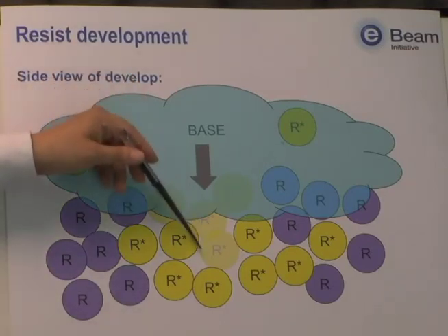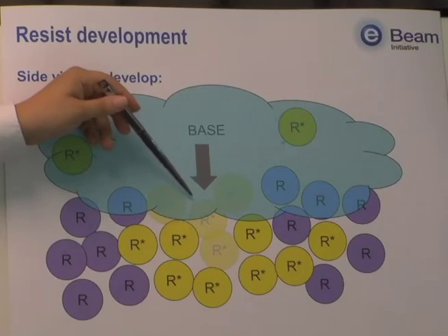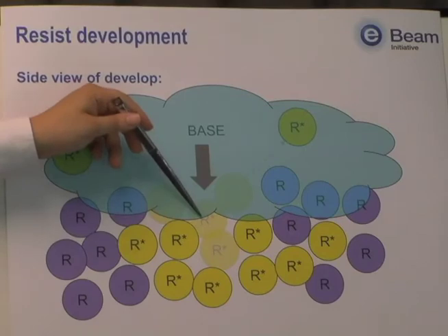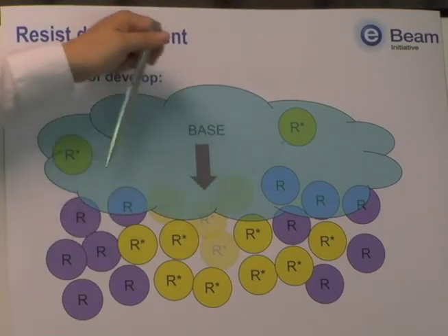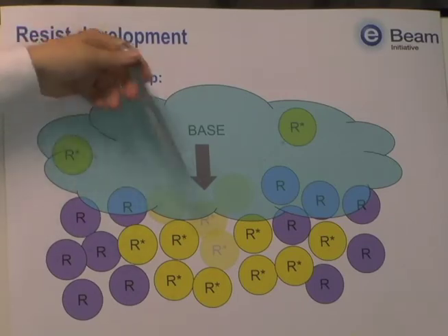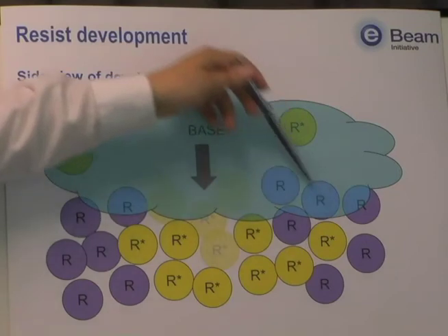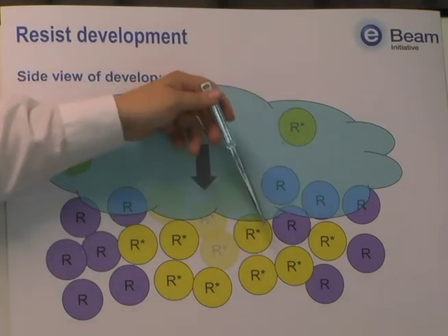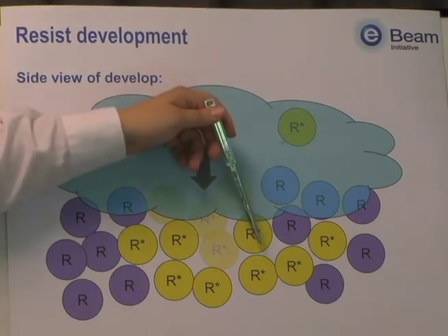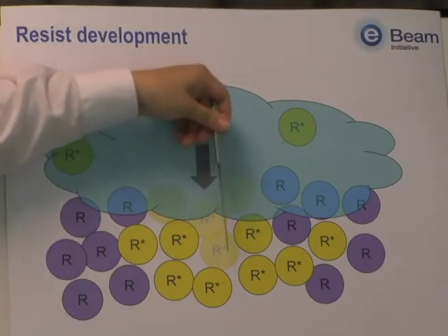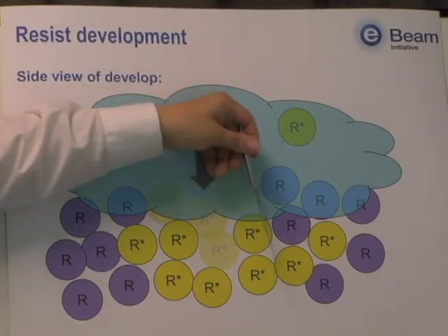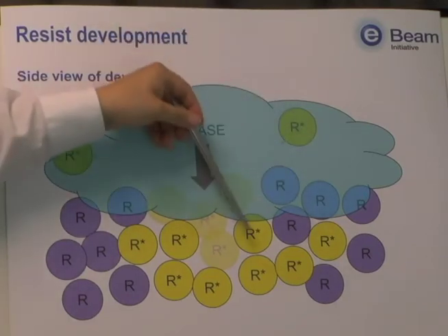Now, the dissolution rate is usually quite rapid vertically in exposed areas of the resist, as one typically sees a fast reaction rate along the resist thickness. Now, because of the acid and other blurs involved, there are non-negligible transitions between fully unexposed as well as fully exposed regions, as indicated in this particular region on the slide. Because of this, development will proceed, but it proceeds quite a bit more slowly in these regions, and you'll find that development after going down will move laterally relatively slowly, as material is attacked from both the top as well as the side.